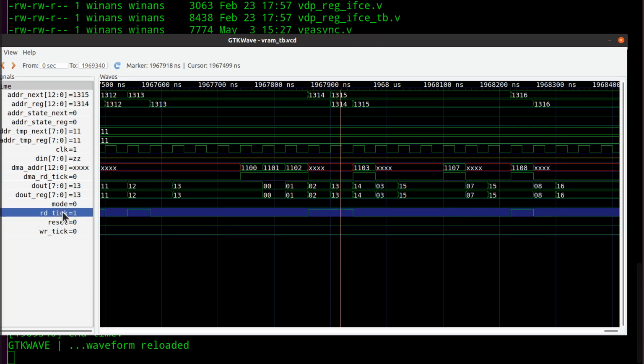All right? Now, we also put the read tick on in this cycle. Now, notice that when I do a read tick here, you see the address advance over here. That's fine, because in this cycle, that address is 13 in this example, which is why you see 13 right there. It's not until the next leading edge over here that the value from this address 14 comes out, and that's what we got. And at that time, we advanced to 15.